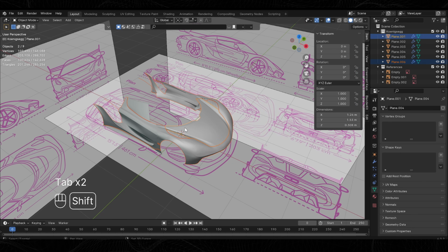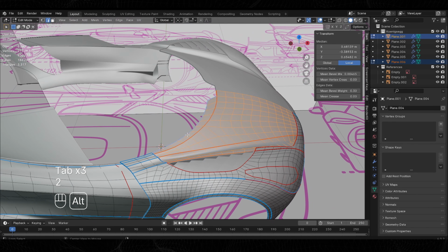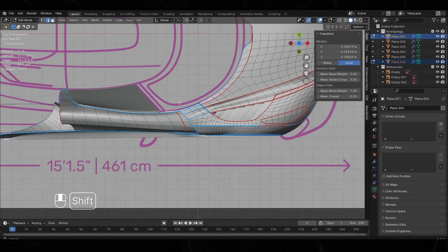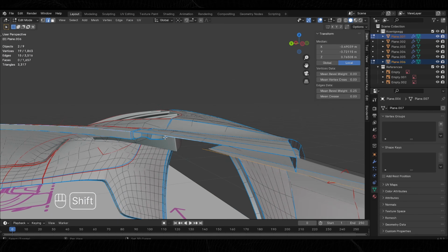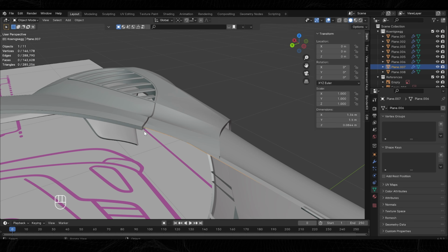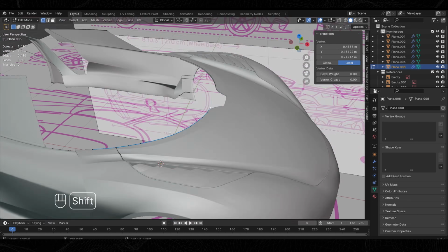The next step is going to be modeling the front windshield. Start by selecting all the vertices around the border of the windshield, duplicate them, and separate them to a new object. Now merge these two. Then connect the vertices to create one big edge loop.